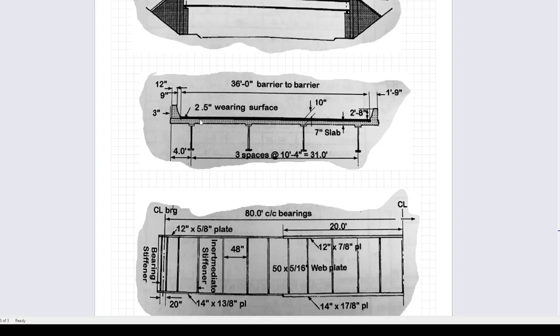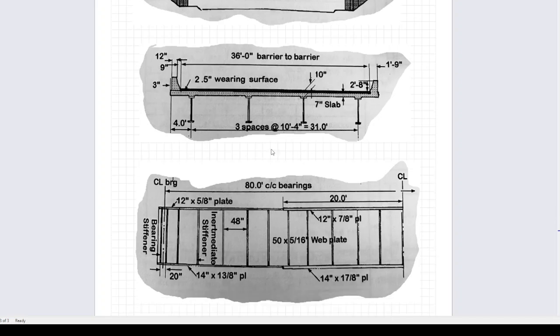So you only need to calculate the superimposed dead load from any diaphragms that you had, the barrier, and the wearing surface.